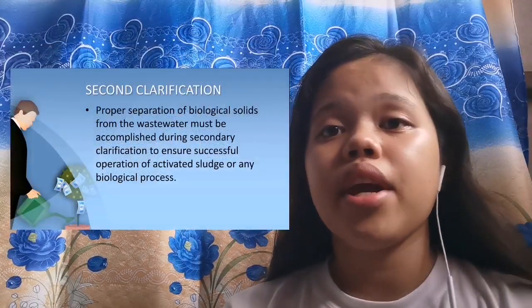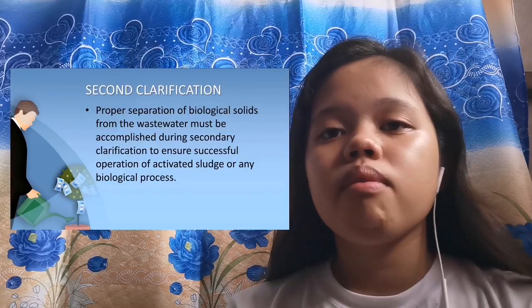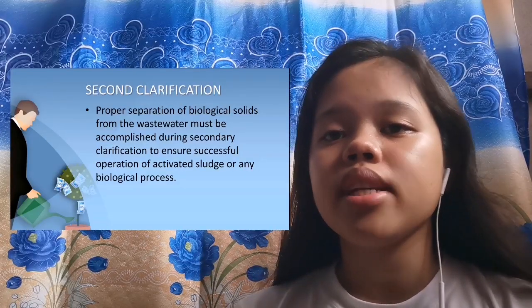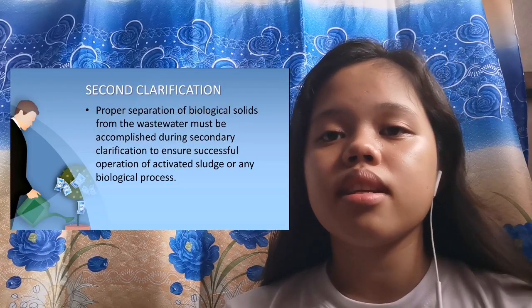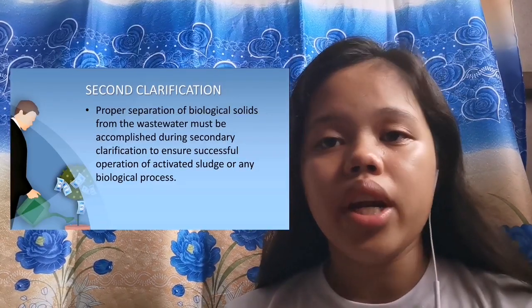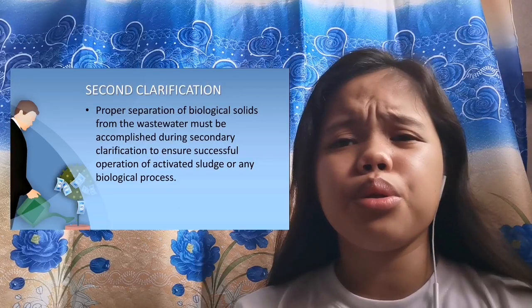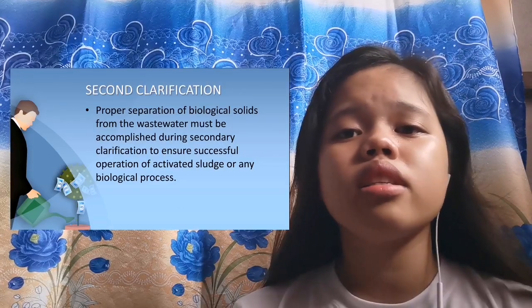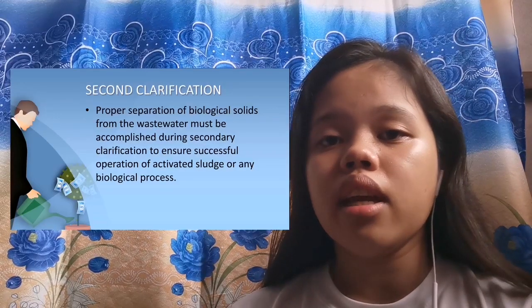Second, clarification. Proper separation of biological solids from the wastewater must be accomplished during secondary clarification to ensure successful operation of activated sludge or any biological process. If biological processes are to operate properly, it is essential that secondary clarifiers be designed correctly, as shown in this picture.